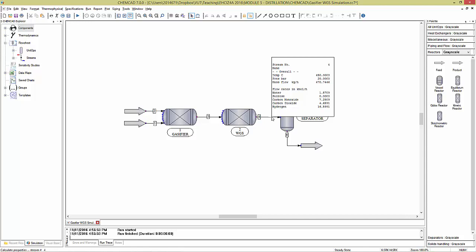We have increased our carbon monoxide slightly, but our hydrogen is still, the ratio is supposed to be, if you look at it, 7.3, maybe supposed to be 14.6 for hydrogen to be right on the molar ratio of 2 H2 to CO. So we still need to ramp up the temperature a little bit.